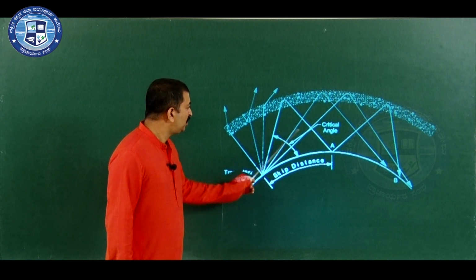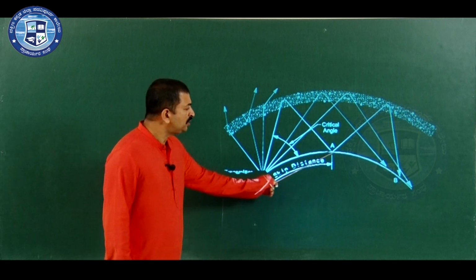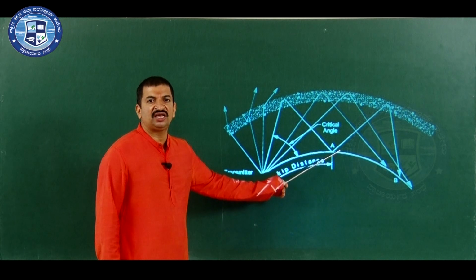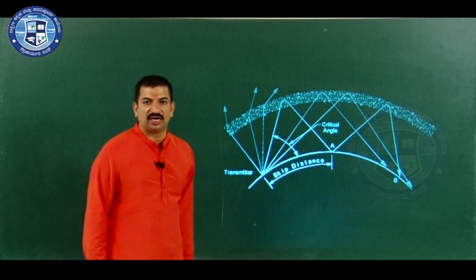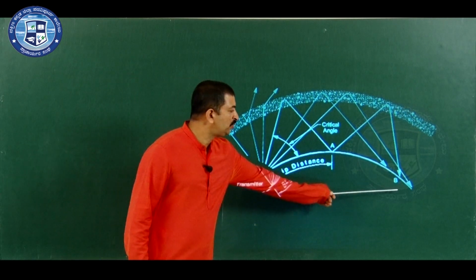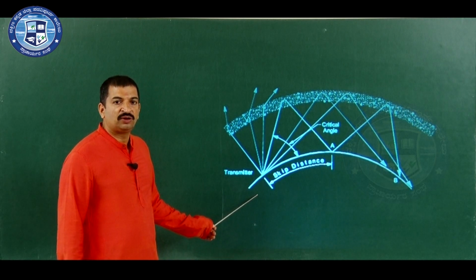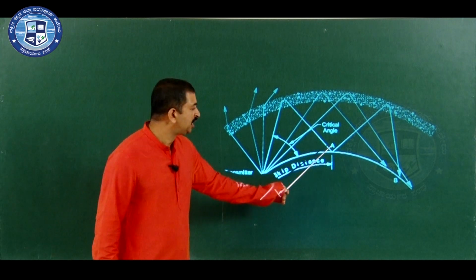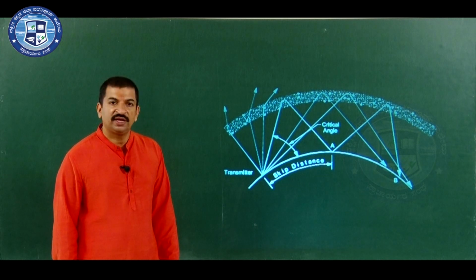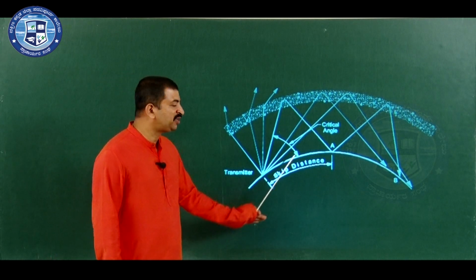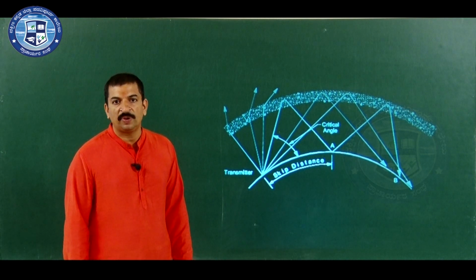Consider the point A receives the signal from the transmitter. The receiver will amplify the signal, it increases the signal strength and it retransmits the signal back to the ionospheric layer. Now, the receiver B will receive the signal from the transmitter, but it will not receive signal directly from the transmitter, it receives the signal with the help of the repeater station situated at point A. So, with the help of these repeater stations, we can transmit signal to long distance, which is called multiple hop transmission.